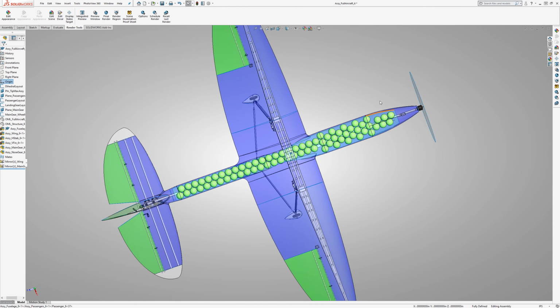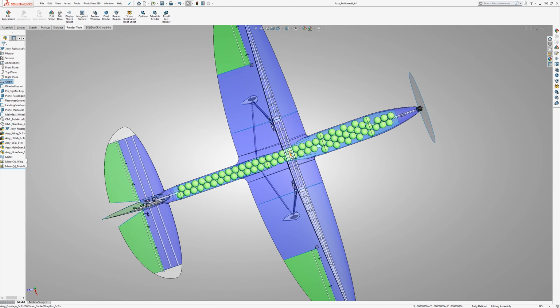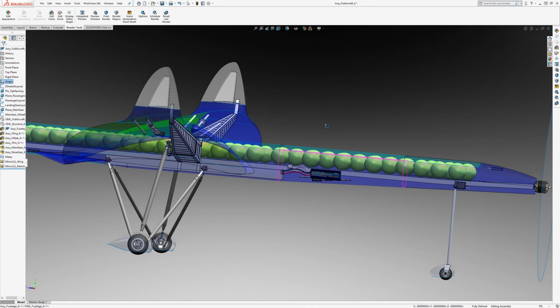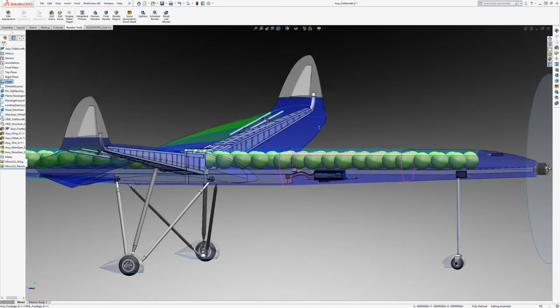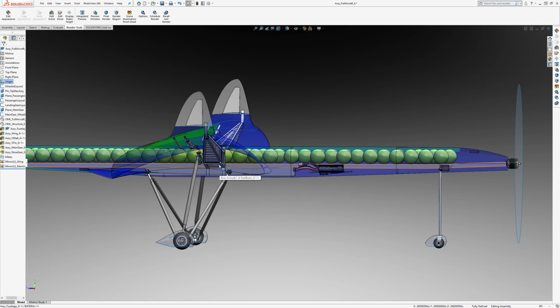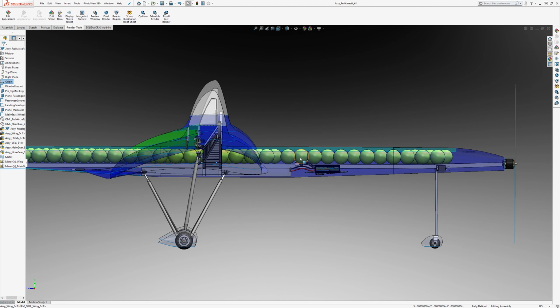And as you're putting in the rest of the components, you can keep track. You can try to get the CG to stay near the origin. And if anything is off near the end of the design, we can always move, for instance, the battery forwards to adjust where that CG is to get it in our intended location.